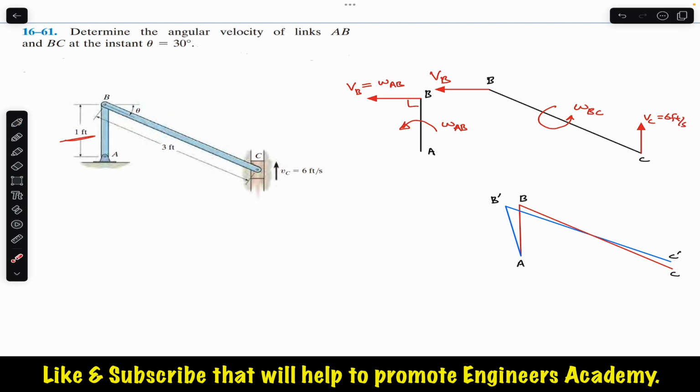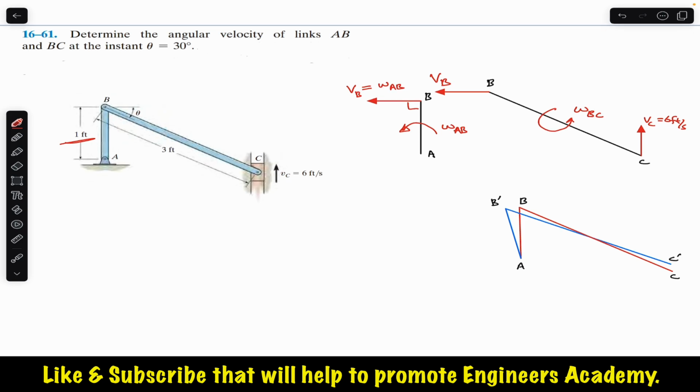And now let's write the relative velocity equation for point B. Let's say that VB is equal to the velocity of C plus the velocity of B relative to C. Now we need to look for the direction of the velocity of B relative to C. This velocity is always due to the angular velocity of this particular link.